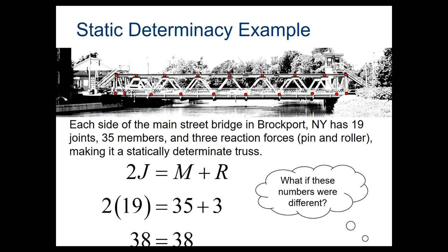This is pretty much what West Point Bridge Design does. If you've ever played with that, it's basically doing the same calculations that we're going to be doing. Obviously a lot quicker than we can do it by hand, but it has the same issue. And that's why, if you ever play with it, it always demands that you use triangles, because it needs to be statically determinate. That's what we need to have happen to get this all to work.